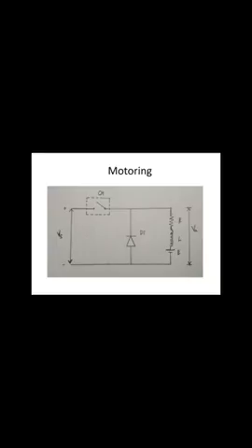During the T-on period, the voltage across the load is the sum of the voltages across the resistor, inductor and the battery. During the T-off period, the source supply does not flow into the circuit. The average voltage across the load is equal to 1 by T into the integral of Vs with limits 0 to T-on. Hence Va is equal to alpha Vs, where alpha is equal to T-on by T. Since the inductor does not have any average voltage, Va is equal to E plus Ia Ra. From this equation, E is found.